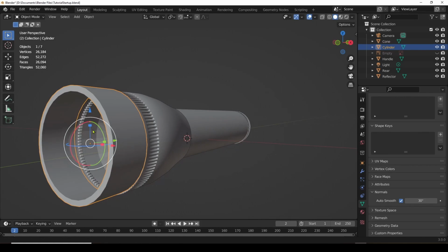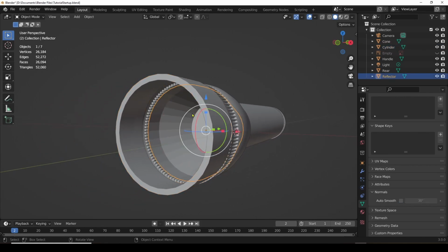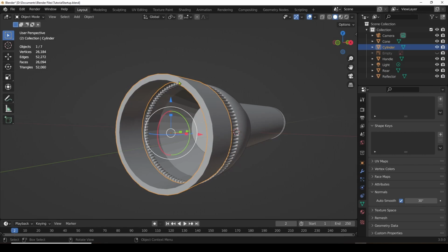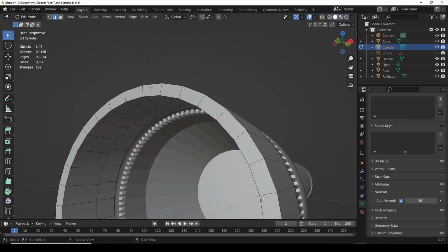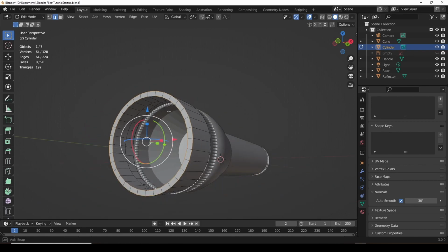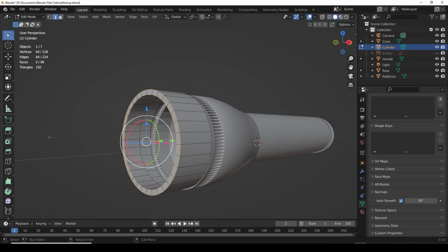One thing I forgot, with this front object, we're going to have to bevel these edges. So we're going to edit mode, and again, we're going to go into edge select. We're going to do Alt, ring select, and to select this other one at the same time, this other ring, we do Shift, Alt, and you've selected both rings so you can bevel them simultaneously.